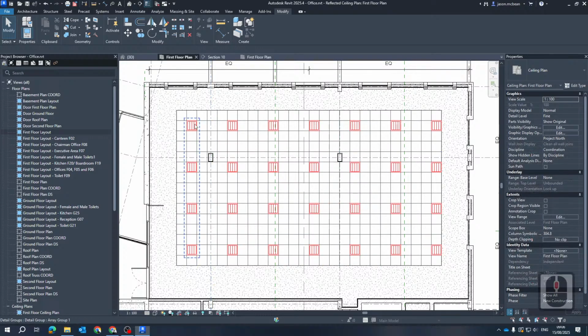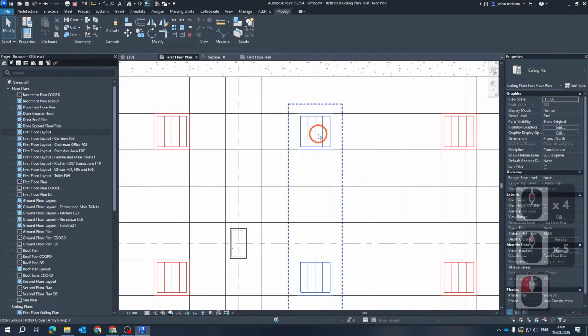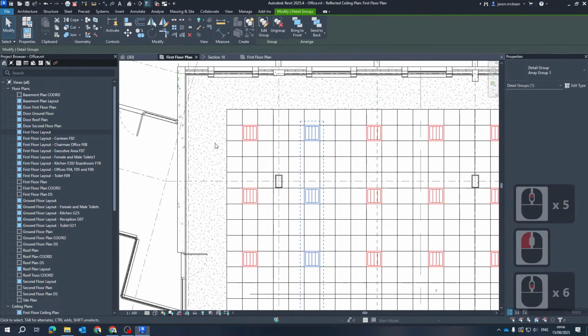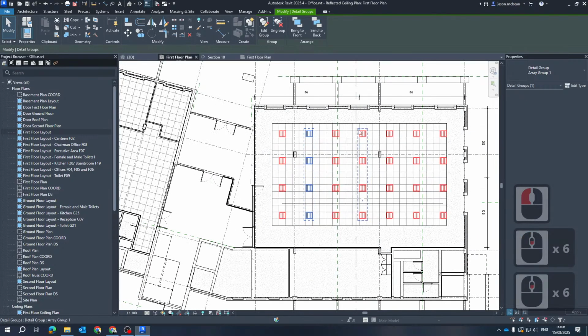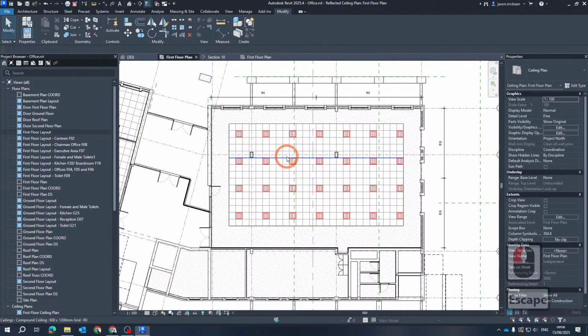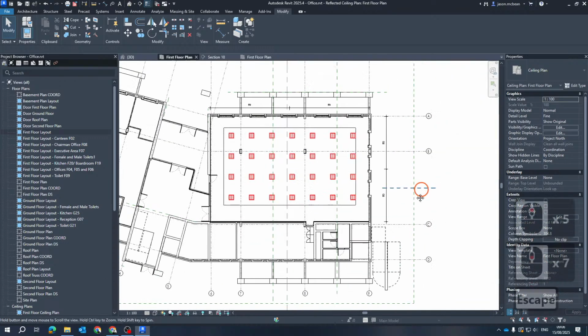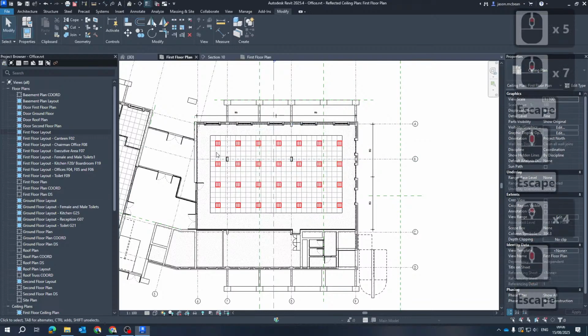There is a requirement for how many of these bays, depending on the lumens for each light fitting, on how the spacing will work. So if you are going to find information with regards to lights, make sure that the lux levels and the spacing requirements for that light fitting are achieved. Osram's website is pretty good at showing this, but I'm going to leave it here, just like this.